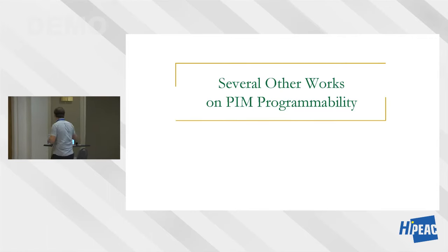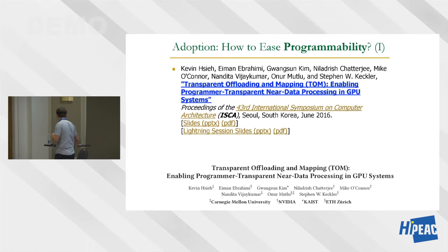Okay, I wanted to go into this a little bit more because, in my opinion, this sort of across-the-stack design is really important. We have several other works on PIM programmability. I'm going to mention some of these later on, but just to give you an idea, we worked with NVIDIA a while ago to do offloading from GPUs. So you have a main GPU, you offload computation, some of the warps that are quite memory intensive, to GPUs that are near memory, and we wanted to do this completely transparently to the programmer. This is not processing using memory, this is processing near memory. I'm going to talk about that later on.